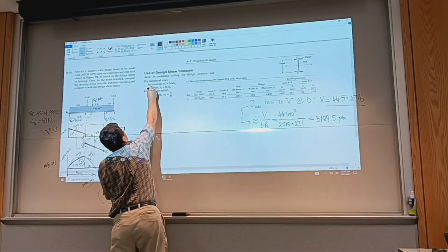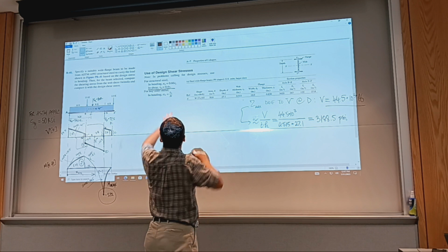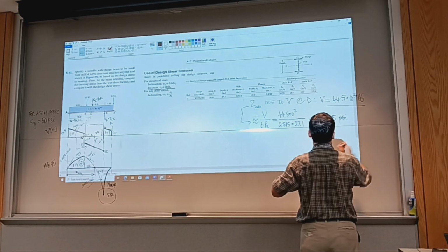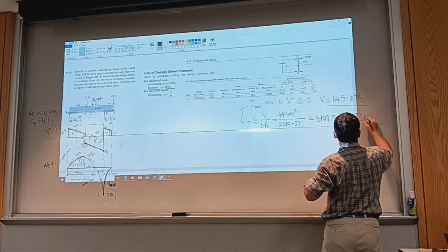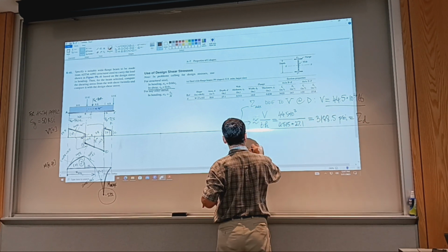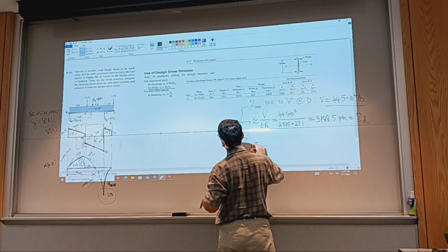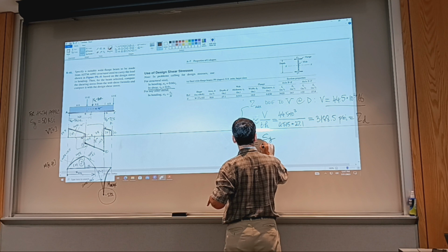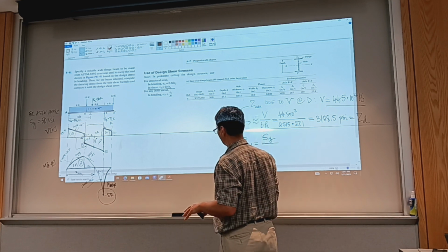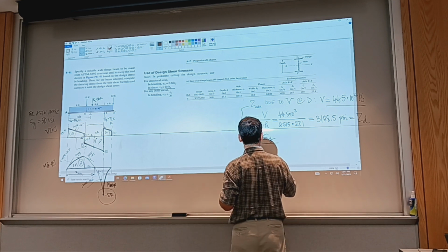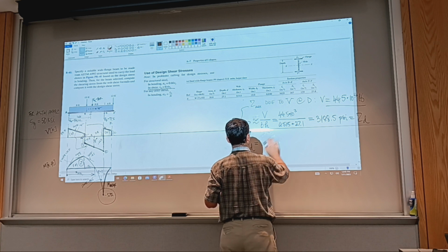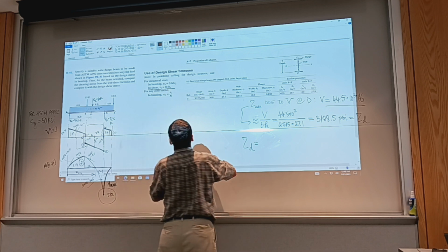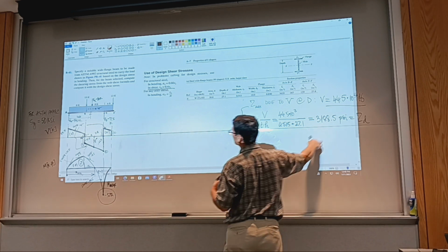This is going to be the design stress. All right, so let's verify the design factor. I'm saying that tau d is the yield strength in tension divided by, what was it? We can just evaluate 0.4 times Sy and compare with the design stress.